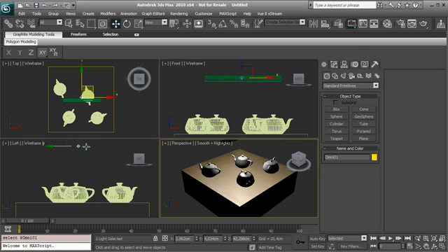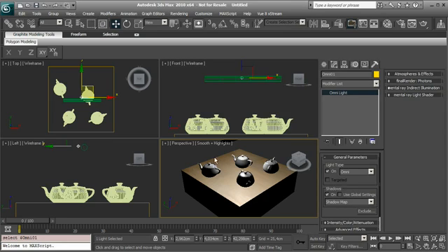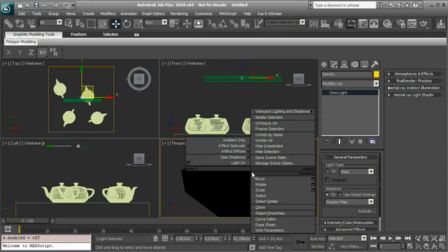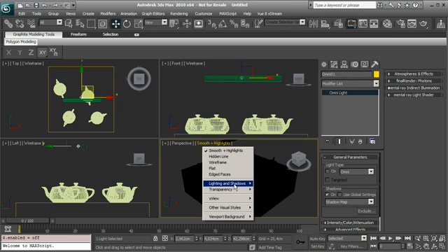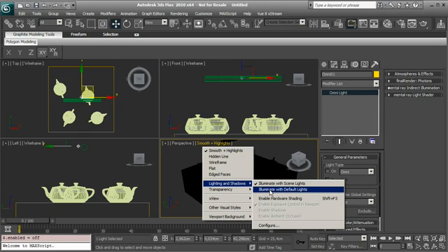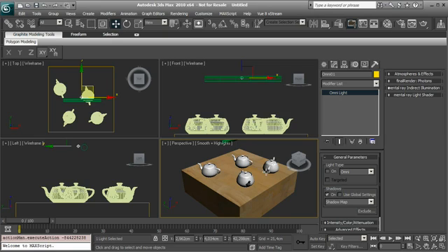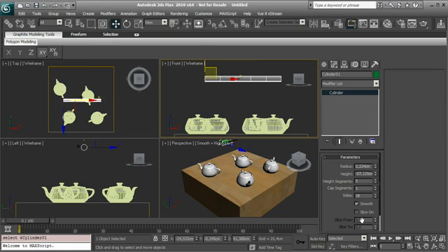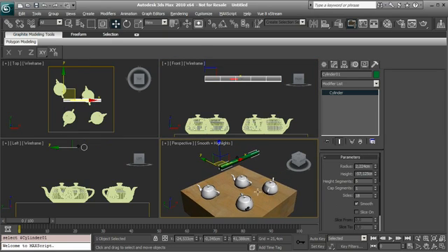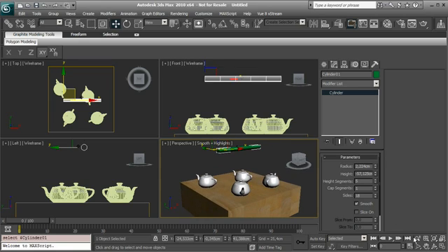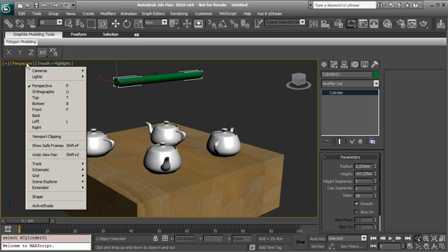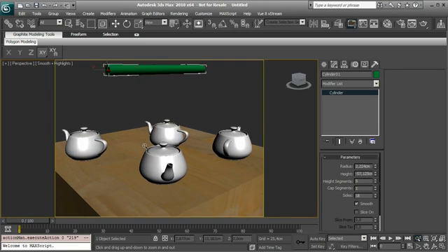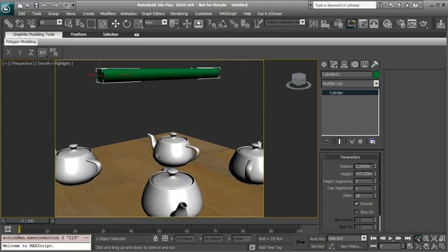we'll use the mesh, the tubular mesh, to illuminate the environment. So let's select the Omni, and let's set it to off. So you see we have no lighting inside the scene. You can go inside Smooth and Highlights, Lighting and Shadow, illuminate with the full light, so we have lighting inside the viewport. Okay, let's go there, and let's go to full screen. Let's set to show safe frame, and we can move it near the camera.